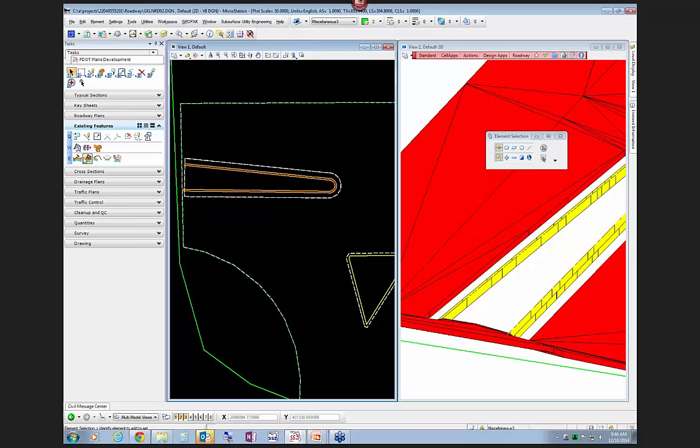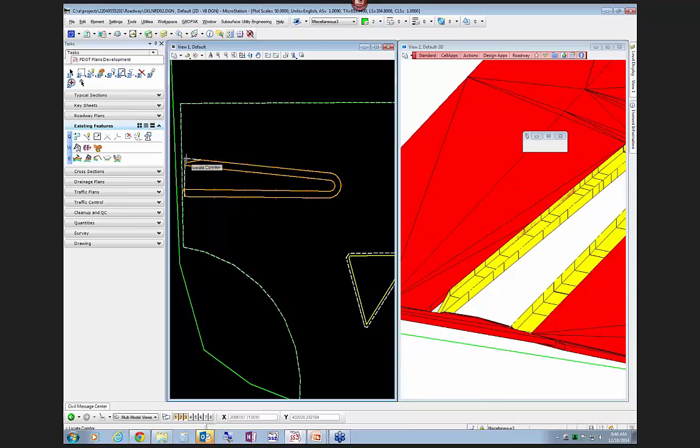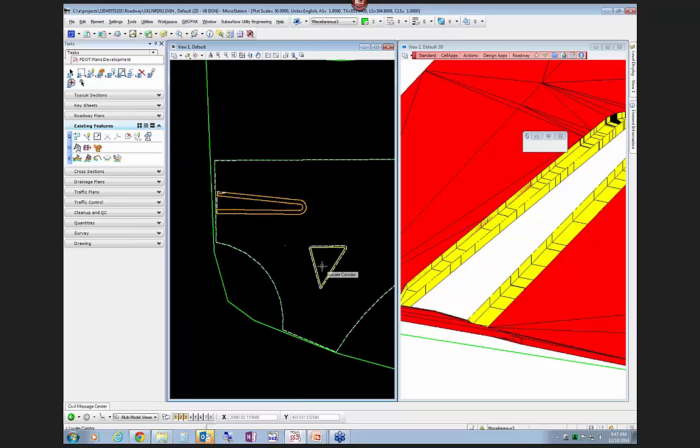And then all I do is go to the add corridor references. I select this particular corridor, or in this case linear template corridor. I'll pick this pavement existing edge as a reference, and when I reset, you'll see that the curb goes all the way out there. Apparently there's a little issue with the end station there, but essentially now I've stretched that out to the existing edge of the pavement, so it's as wide as it needs to be. And that's how you do curbs.